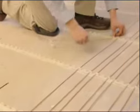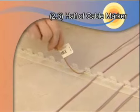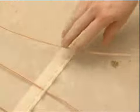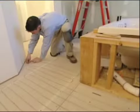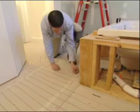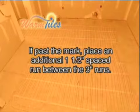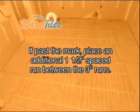Continue laying out the cable until the 1/4 or half of cable length label is reached. Compare the location of the label to the corresponding 1/4 or half point previously marked on the floor. If the label has not reached the location marked on the floor, leave the low traffic area unheated. If the label has passed the mark, carefully lift the previous few cable runs and place in an additional 1.5 inch spaced run between the 3-inch runs to use up the excess cable. No more than 2 1.5 inch spacings should be run before another 3-inch spacing interval is installed.